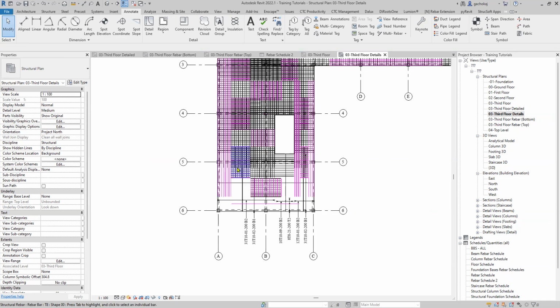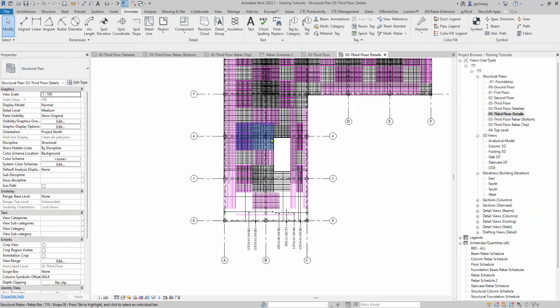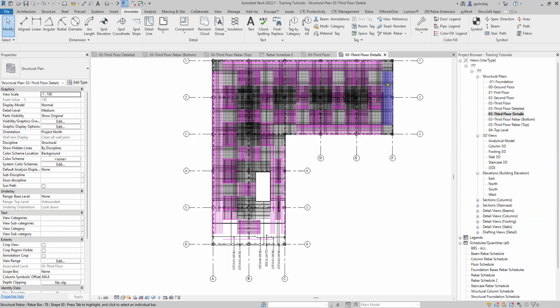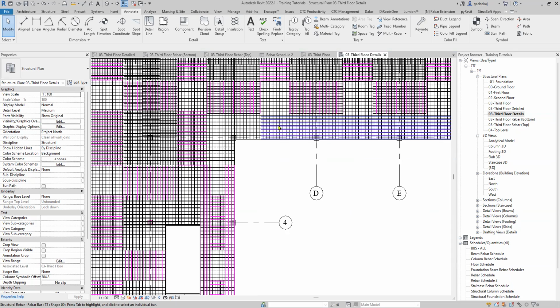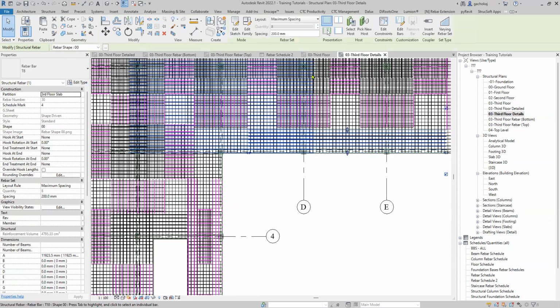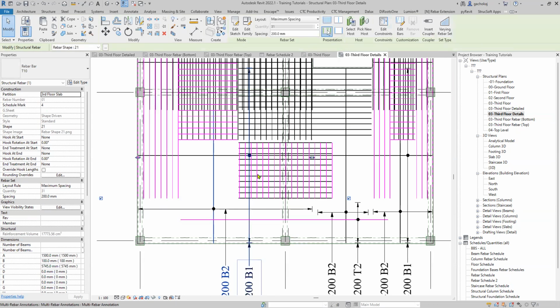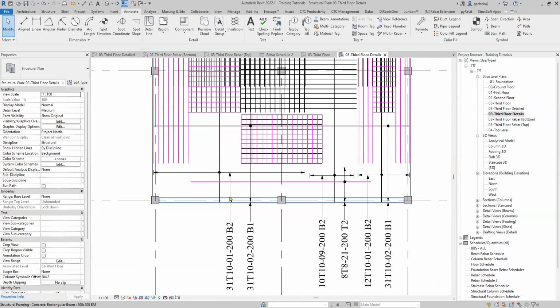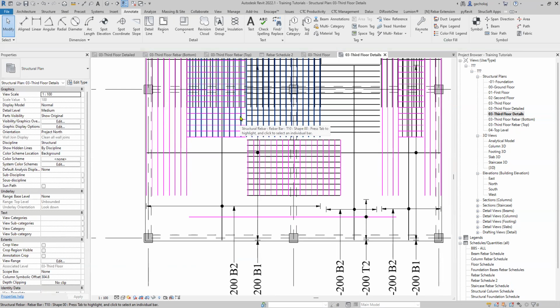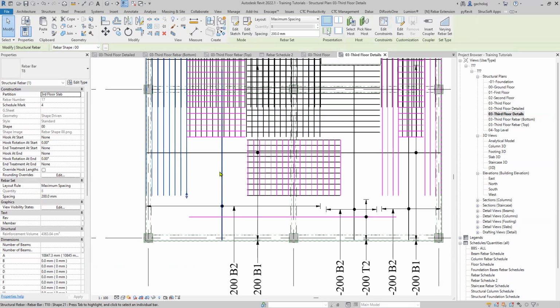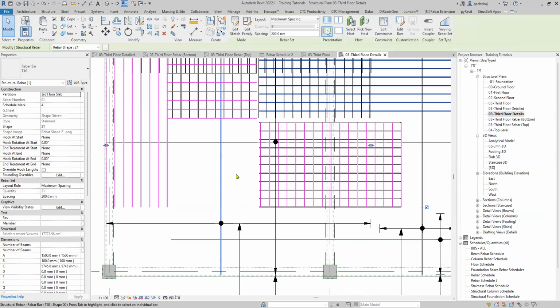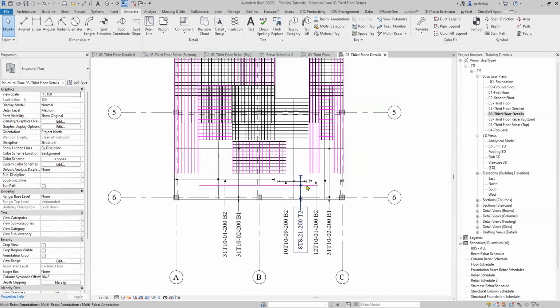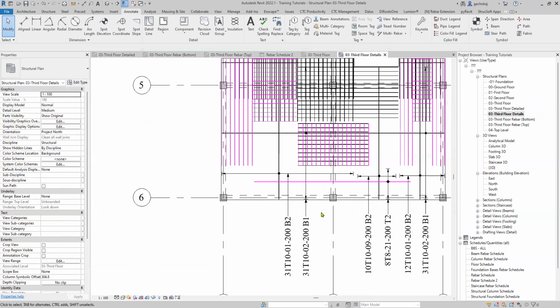So if you continue doing this and showing middle, your slab will continue clearing up. And by the end of it, you should have no bar showing all. All bars should show just one bar. It may be the middle bar, or in this case, like here, I changed the presentation. It still shows one bar, but you change the location. Maybe show middle might be a bit untidy. So you can just choose under presentation which bar to show. Make sure just that your work is neat and it's visible.